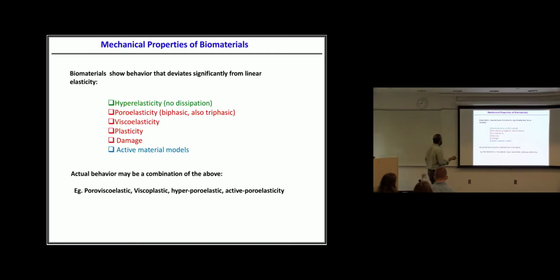Okay, very good. So the second type of material response is called poroelastic. Poroelastic basically means a material has both a solid component and a fluid component. So there is water, which is everywhere, right? A significant percentage of a cell is water. A significant percentage of your body is water. I think it's 75%. So then you have to account for two phases. These poroelastic models are also called biphasic models, and the theory that describes this is called poroelasticity.